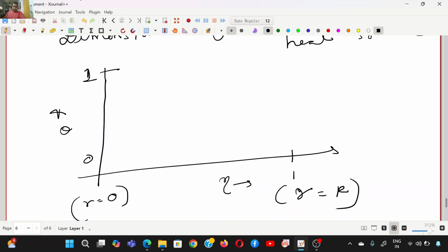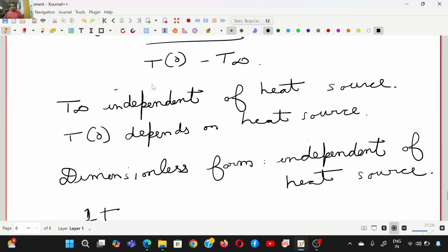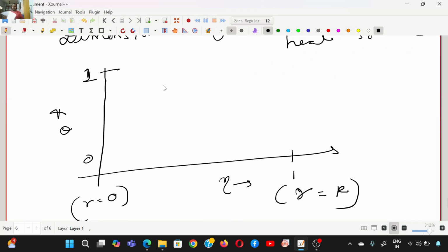So at various Biot numbers, what is theta? This is our expression, right? I'll just write the equation in a small form over there. So theta here is equal to (2 plus Bi) times (1 minus eta square) divided by (2 plus Bi). So when Biot is equal to 0, theta is just 1 minus eta square by 1.